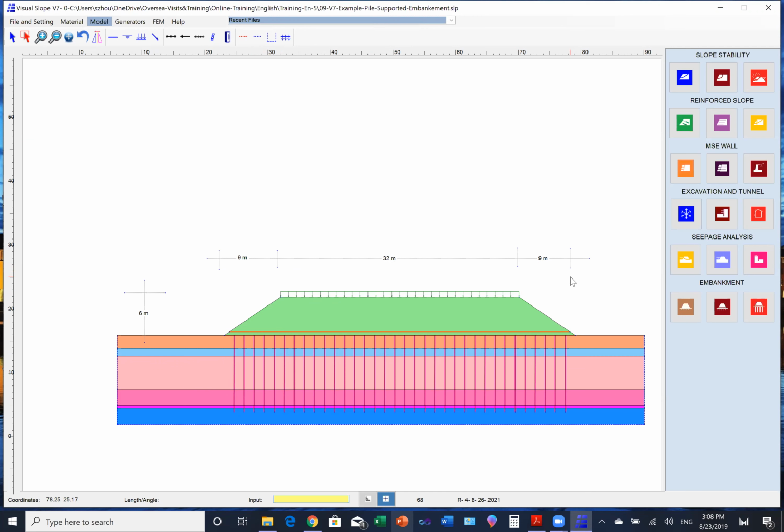And we have a surcharge on top. We say it's a traffic surcharge. It can either be enlarged as, say, a composite foundation. Here we have some soft layer soils, and the bottom one is a stronger layer, which is a bearing layer. So if we put the embankment directly on the soil, we will have a large settlement.